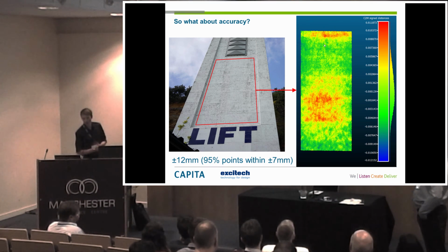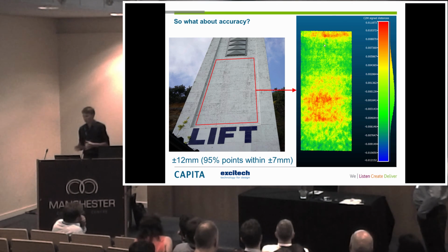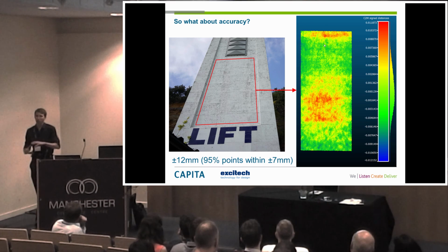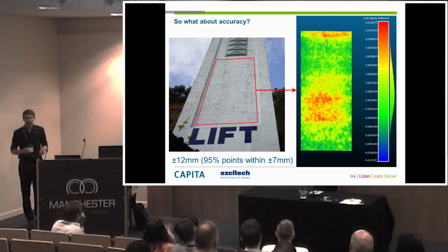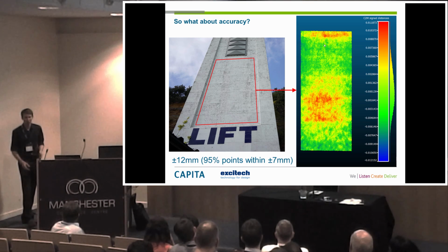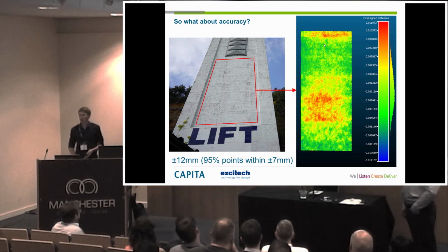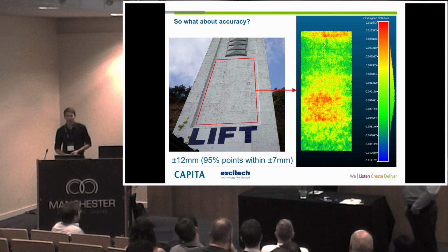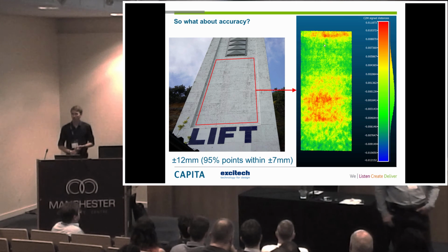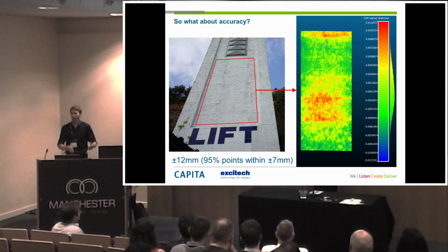Accuracy with this. So this kind of comes on to that question about how you scale it up. With this, all the computer's doing is taking a huge amount of photographs, joining them all together, finding common points to build you this 3D model. From a photograph, as you know, you can't get scale from it. If I take a photograph of this table, the computer can't tell how deep that is, how high it is. So what we need to do is have reference markers, whether that's something on site, maybe a standard brick size, maybe you know the width of a door, or maybe you put those little black and white targets around the place. You need some kind of marker on site that you know the size of. So we could say on this lift, we know that the lift gate is 2 meters wide. So when we get that model back, we can scale it up and say that is 2 meters. And it will then process into the right size.